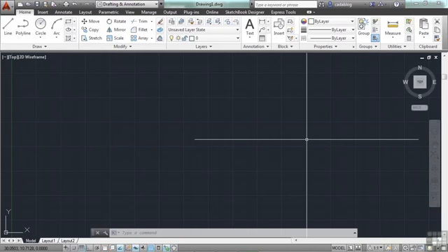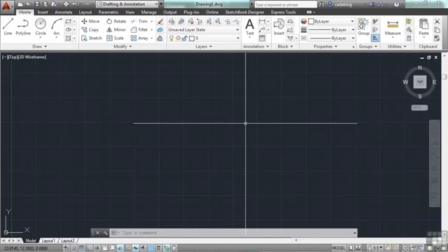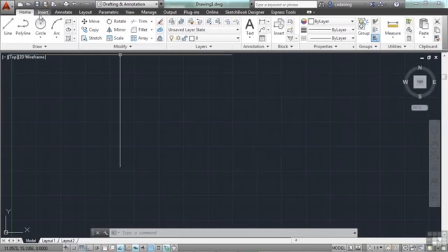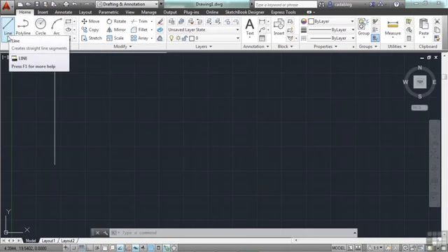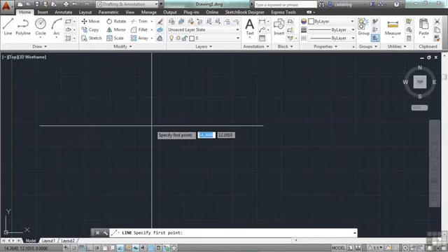So it's also one of the easiest objects in AutoCAD to draw. You just pick two endpoints. Just 2 clicks of the mouse and you're there. But even though a line is very simplistic, there are many ways to draw a line in AutoCAD. To start the line command, you can go to one of several different places. You can use one of several different methods. It's up to you. On the ribbon, on the Home tab, the first panel, which is the Draw panel, you have the first icon, which is for the line command. Click that, and your command is started.